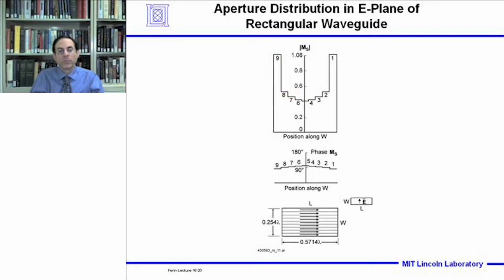So what this shows is the magnetic surface current, or the electric field, is not uniform across the aperture, that approaches a maximum value at the edge of the elements. And what we're going to show later is when the array element is embedded in an array, that this shape will change, it becomes more uniform.